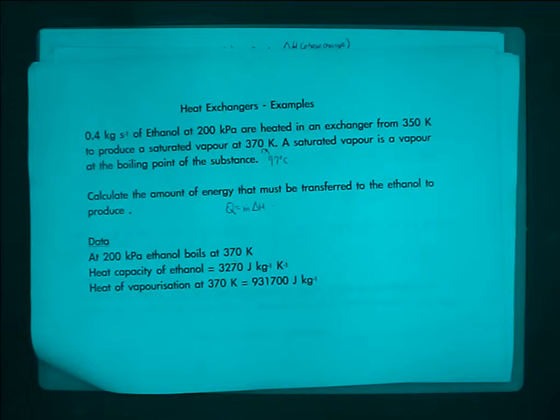Yeah, so here it will be like 273 to 350. If it's 350, 370, then there will be no changes. Yes, there will be a change, the temperature at which it is starting, and the temperature at which you produce the vapor. If you were stopping here, then you wouldn't be vaporizing. We only have our liquid that is just about to vaporize. In order to make it vaporize, you need to pass through the heat of evaporation. You look at the chart that will look like that. The heat of evaporation will basically make the change from liquid to vapor. That is the heat that we need to add in addition in order to make the phase change.